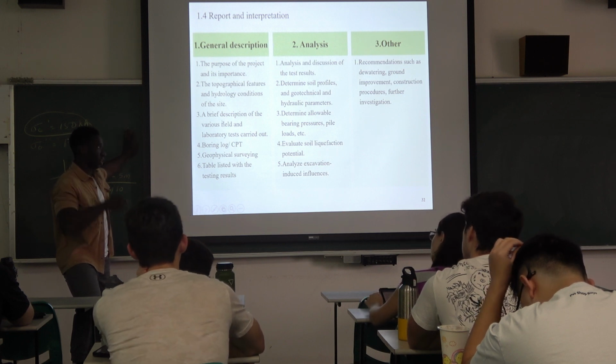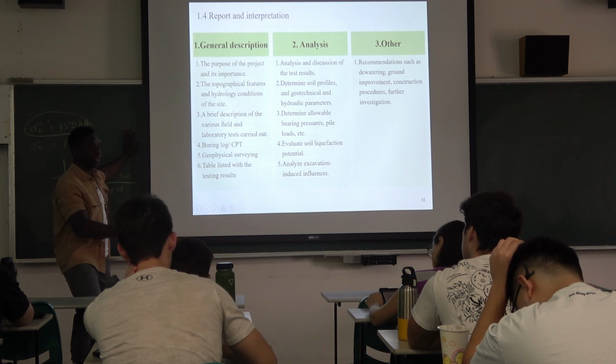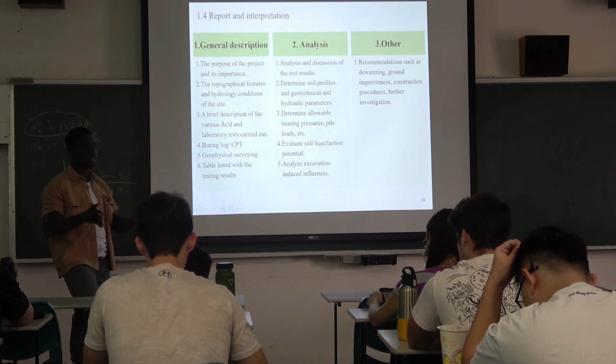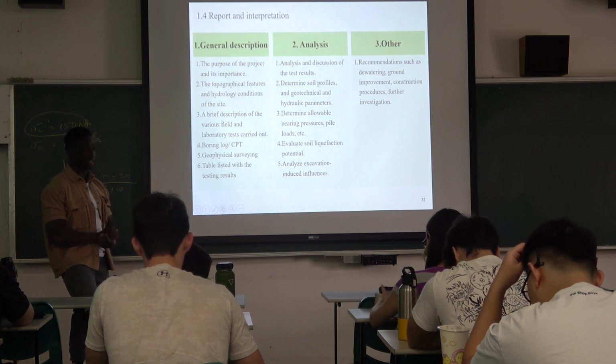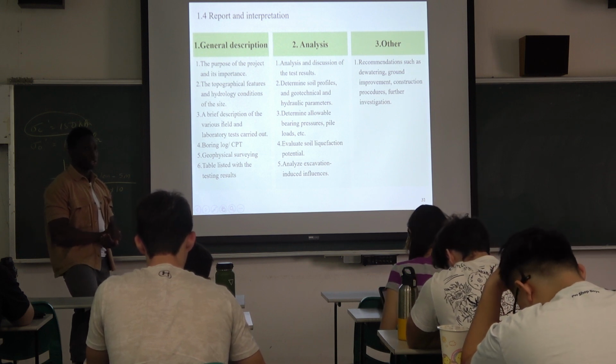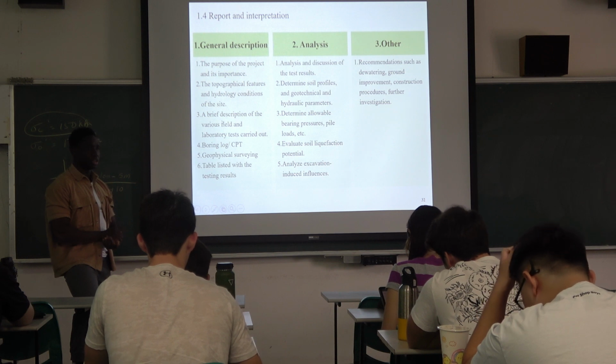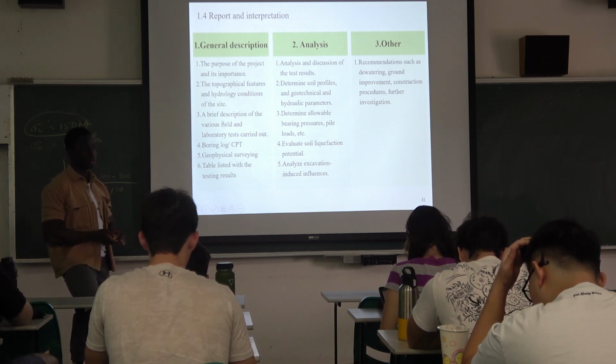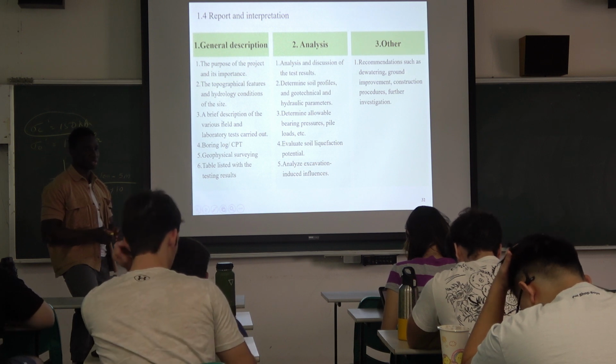So you have to take that into consideration. If I excavate this area, how is it going to influence the buildings or structures nearby? Because if you don't take proper measures, the excavation in your site will collapse and the nearby buildings will also collapse. Now you have a much bigger problem.